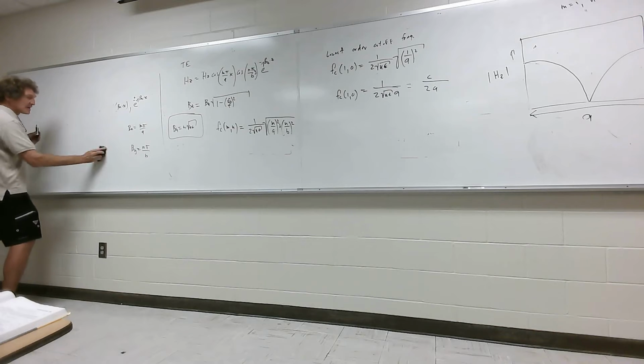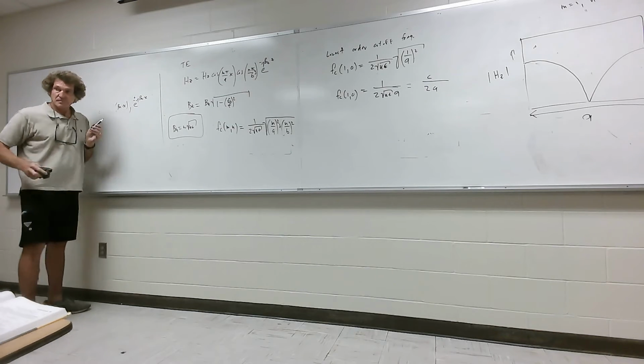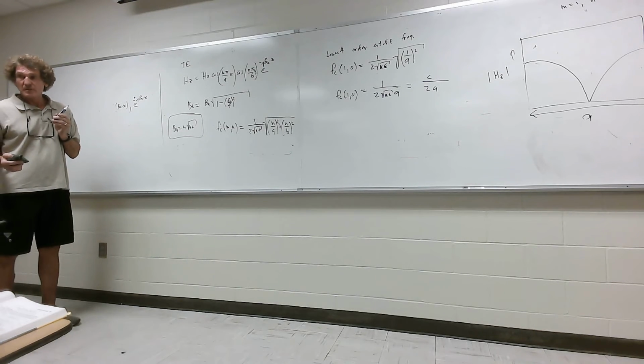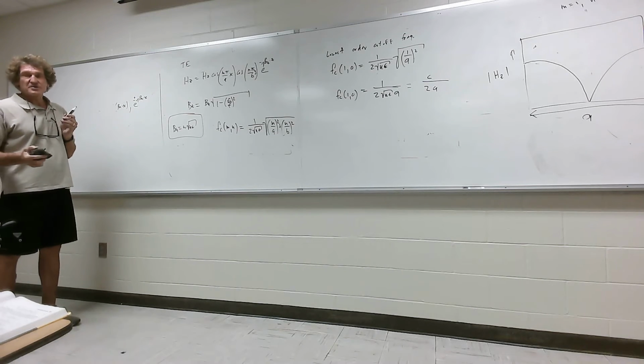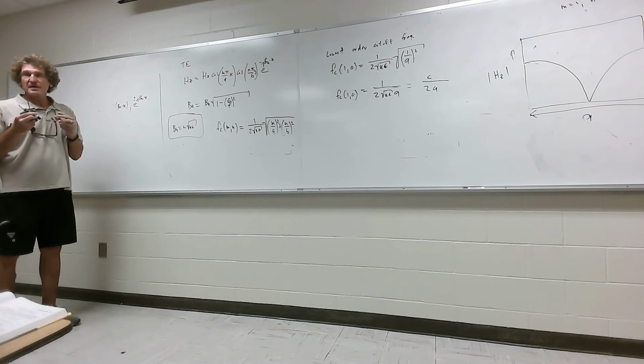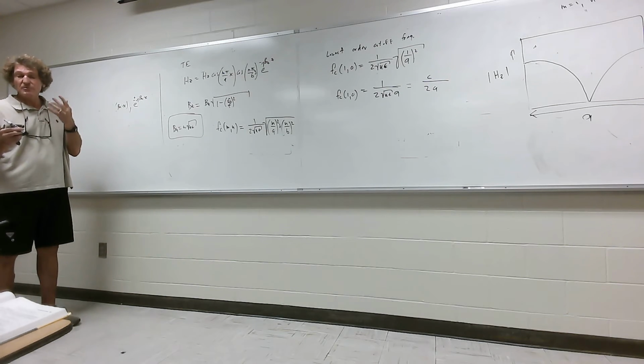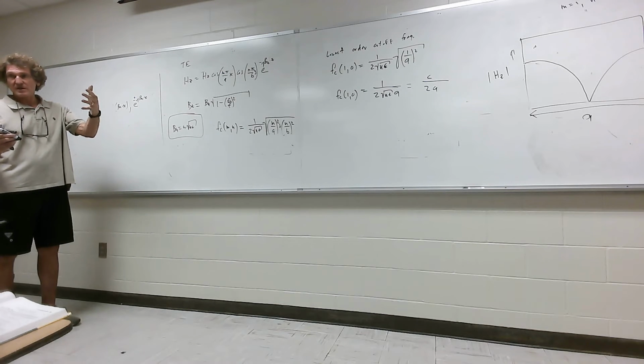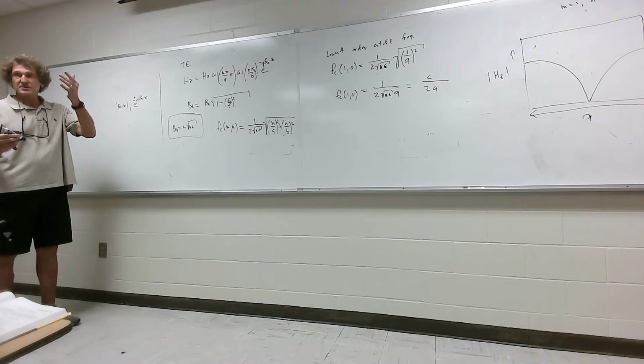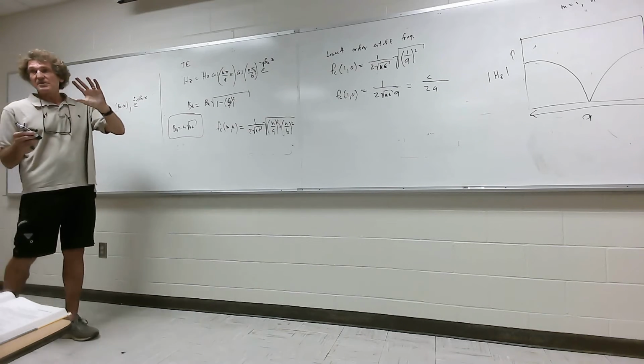So, now. Would there ever be any advantage to having a waveguide that operates in a higher mode? Well, there are specialty cases. But the problem is, the minute you have a higher order mode, like a 2-0 mode, you've got energy propagating at 2 different velocities. So how do you know how much energy is at the 1-0 and how much is at the 2-0? Frankly, you don't, but what they do is this.